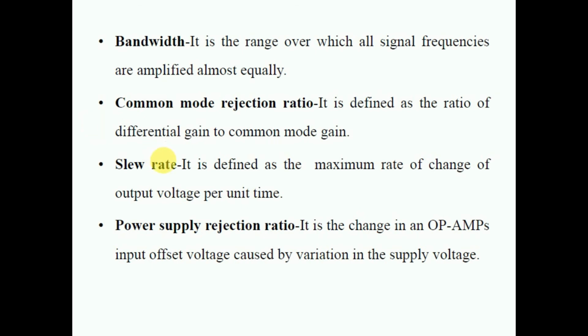and hence you will achieve the voltage gain of the operational amplifier. In the same way, if we provide both input terminals with a common signal, then it will provide some kind of output, or we can say the common mode gain. Whatever gain appears at the output terminals is considered the common mode gain, and the ratio of this differential gain and common mode gain is called the common mode rejection ratio. So that's it for the common mode rejection ratio.